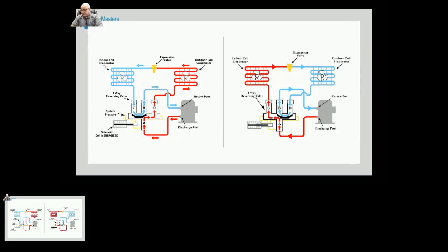But it doesn't mean the direction of the flow is going to reverse in the compressor. So for example, when I say the reversing valve, it's also very popular, very well-known thing. When I say a reversing valve is reversing the direction of the flow, I'm not saying it is reversing the direction of the flow in the compressor here, okay? It is not.